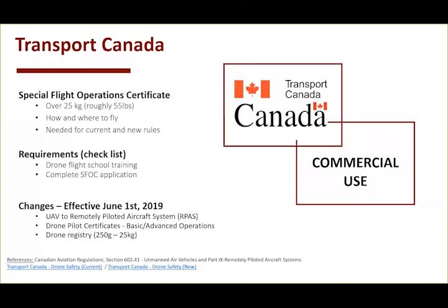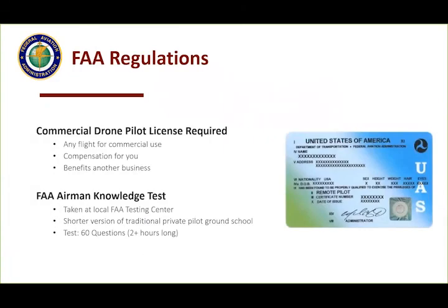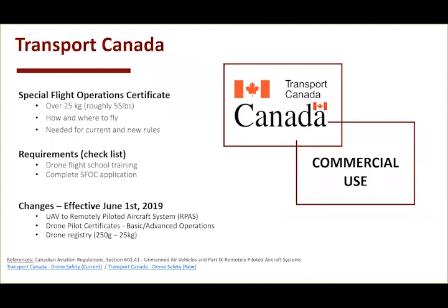Perfect. A couple other questions here. Do you have to enter an elevation for your ground control points? Well, if you look to fine-tune the data with ground control points, then you're either acquiring those measurements with a GPS system, or working with local coordinate information, like a total station system of some type, where you're taking the XYZ data from the mapping of those control points and utilizing them as a local coordinate.